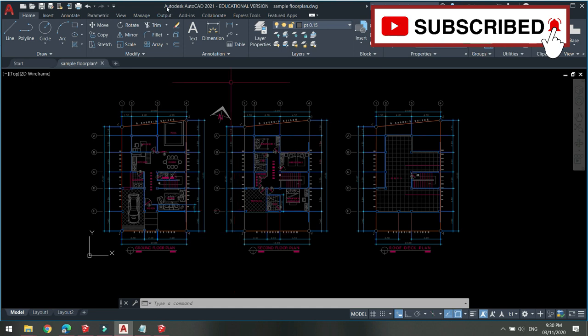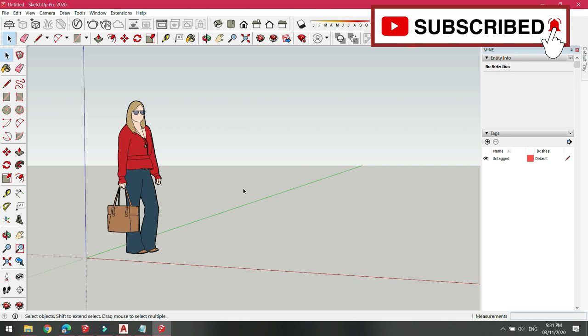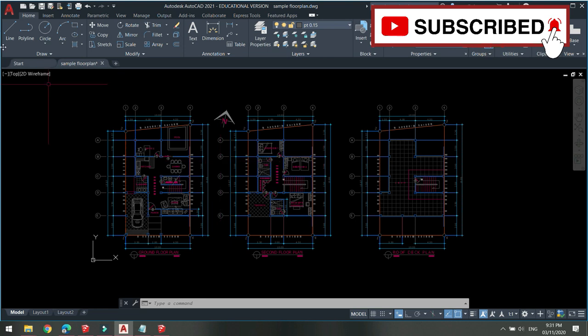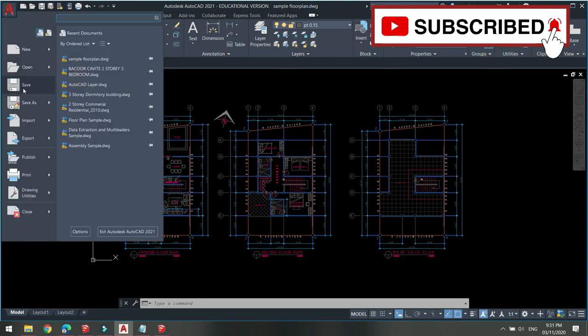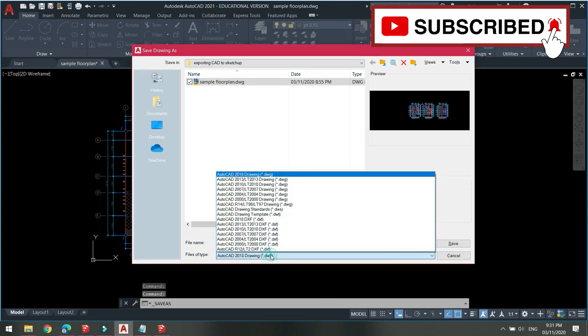So since my AutoCAD is 2021 and my Sketchup is 2020, the version of AutoCAD is 1 year higher than my Sketchup. So what does it do? Actually, it means that if I import that file inside Sketchup, there are compatibility issues. So for safety reasons, I should save this file into a lower version of AutoCAD. So I'm going to select this and save as. And then I'm going to click a lower version.